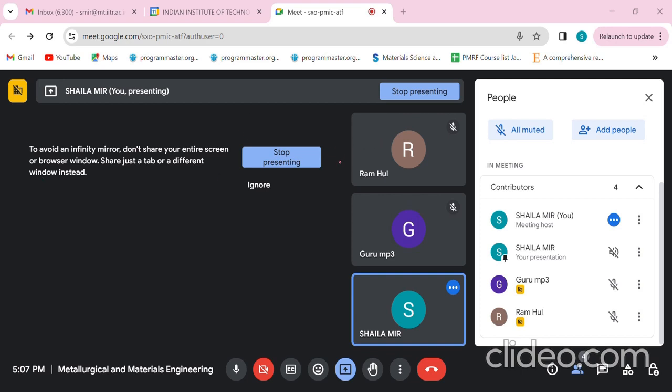It is C, ma'am. Dislocation is perpendicular to dislocation. Okay, so actually, yes, we know that screw dislocation is not inclined at 45, so that is a wrong option. The other option is that edge dislocation is parallel to dislocation line. The right option is that it is perpendicular to the dislocation line when we are talking about edge dislocation. And then it says that screw dislocation is perpendicular to dislocation line. That is wrong because screw dislocation is actually parallel to the dislocation line. So option C is the right option.